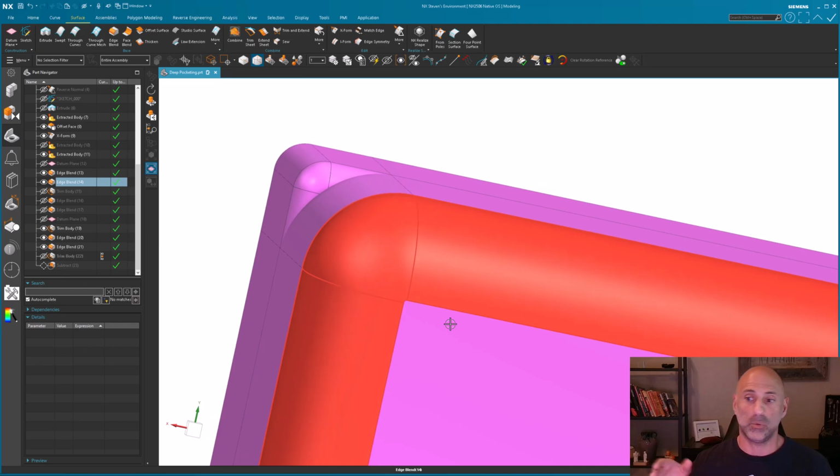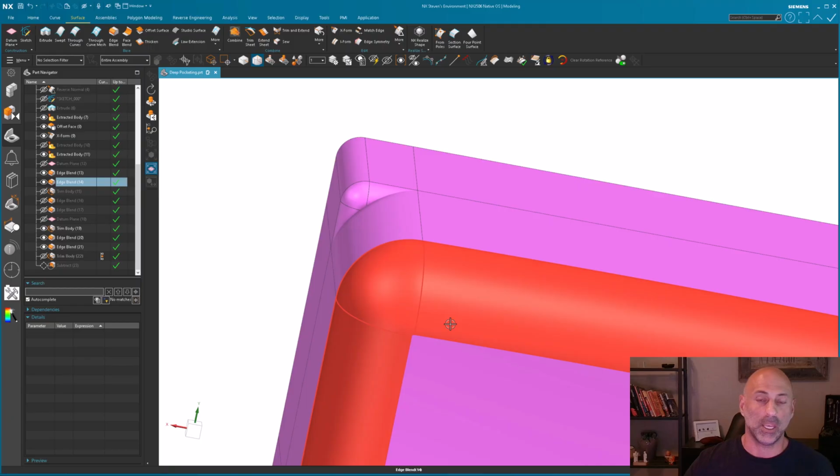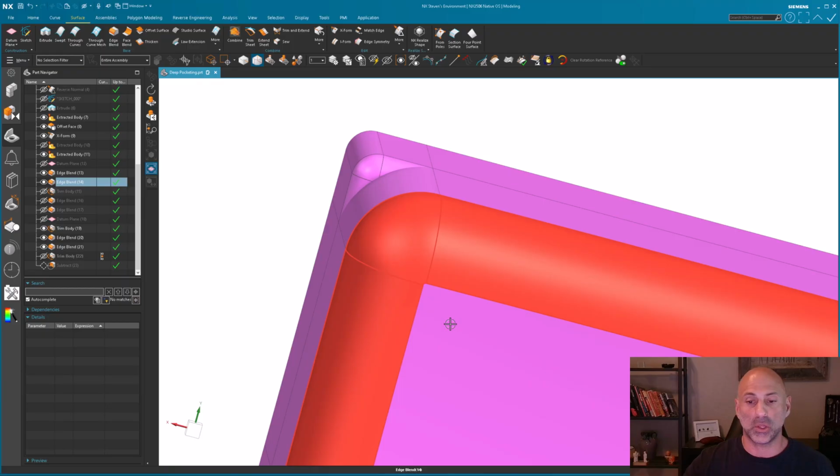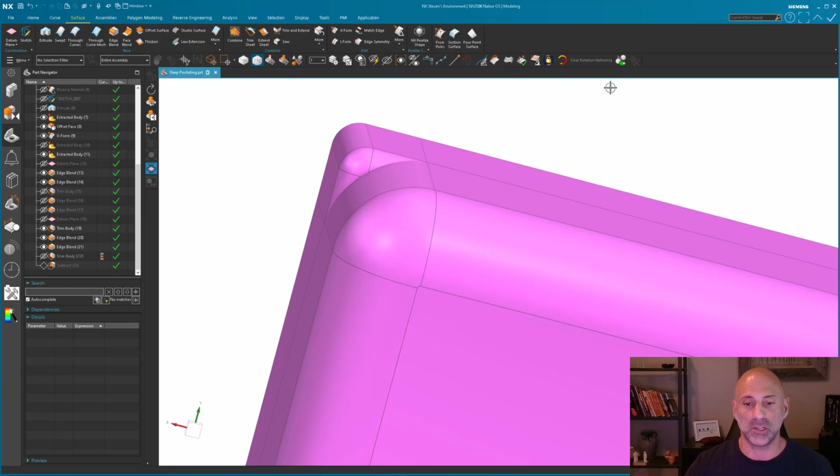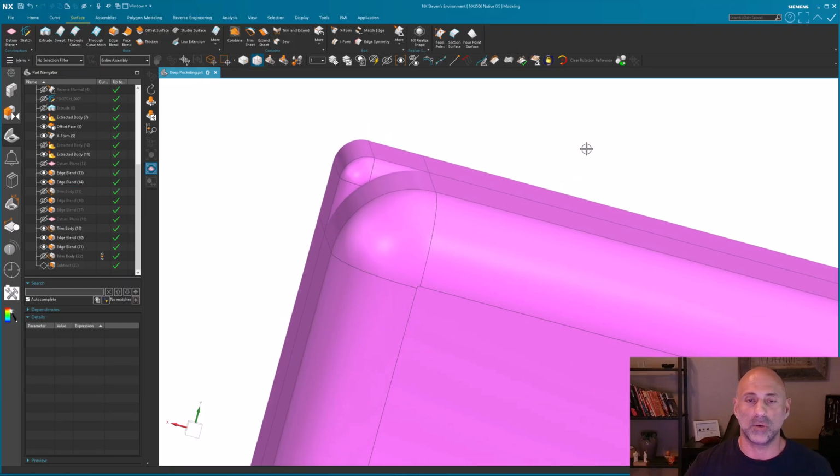Okay, you don't want those sudden stops and changes, as I mentioned, because those sudden stops and changes, again, can impart microscopic little undercuts, potentially chips, something on the surface that leads to potentially a stress riser and other things. So being very thoughtful about what's happening in these scenarios is going to go a very long way.